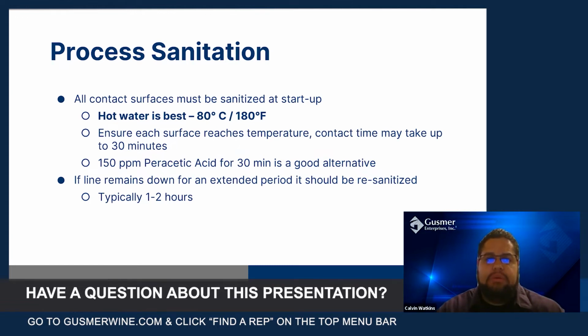What we recommend for good sanitation is making sure all contact surfaces at the start of your process reach 180 degrees Fahrenheit for 30 minutes, and hot water is really the best way to get there. Temperature plus time is a good way to sanitize all of your surfaces.